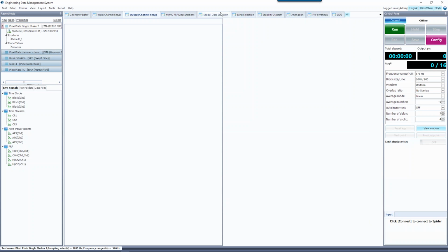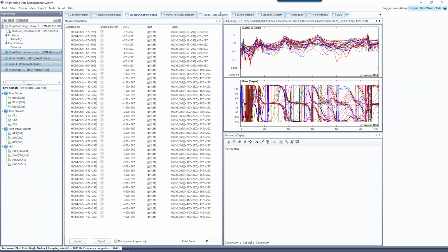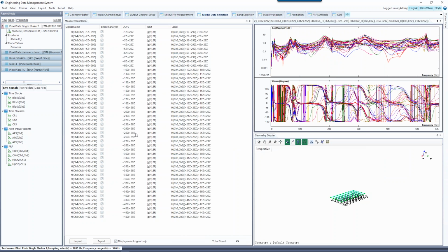But still the same, you need to go through this number of delay blocks and number of cyclic, or say, time average blocks. So the testing time will be increased dramatically. So that's the reason a burst random is more popular, being used rather than that. But for some situations, you want a very nice clean result, you can go to this pseudo-random or theoretical random.